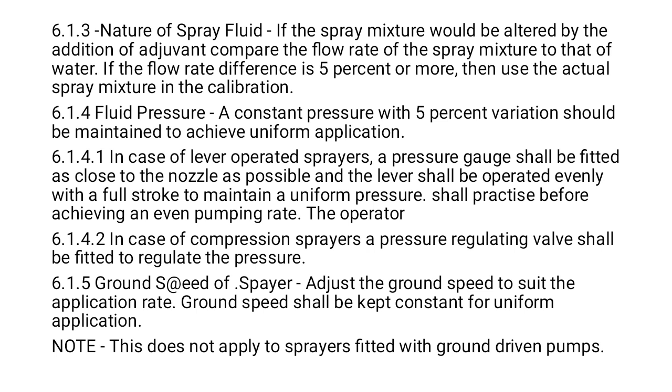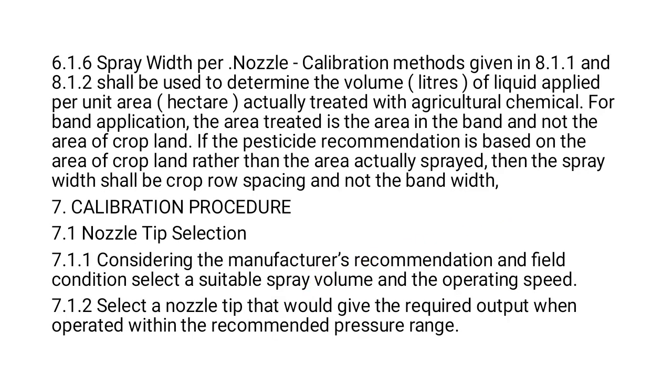In case of the lever operated sprayer, the pressure gauge shall be fitted as close to the nozzle as possible, and the lever shall be operated evenly with full stroke to maintain uniform pressure, and the operator shall practice before achieving the even pumping rate. In case of the compression sprayer, a pressure regulating valve shall be fitted to regulate the pressure. And ground speed of the sprayer: adjust the ground speed to suit the application rate, and ground speed shall be kept constant for uniform application, and this does not apply to sprayers fitted with ground driven pumps.